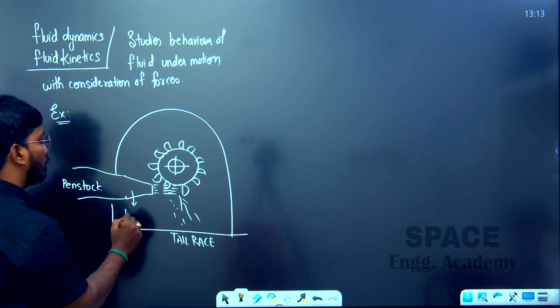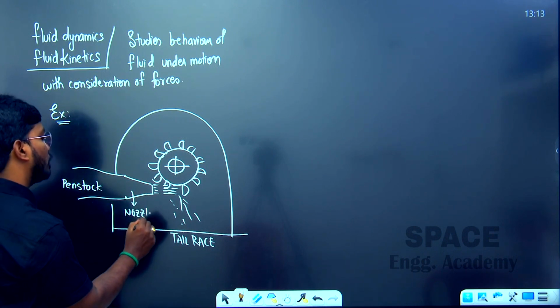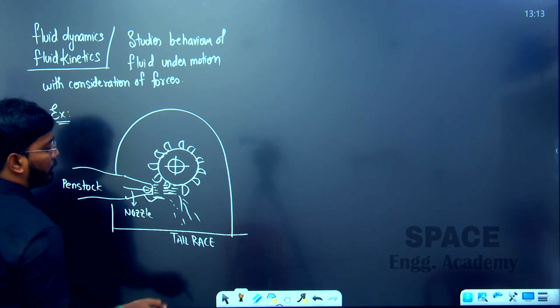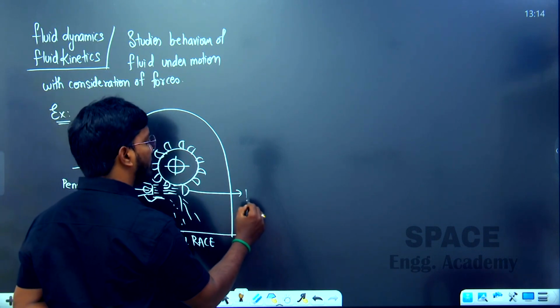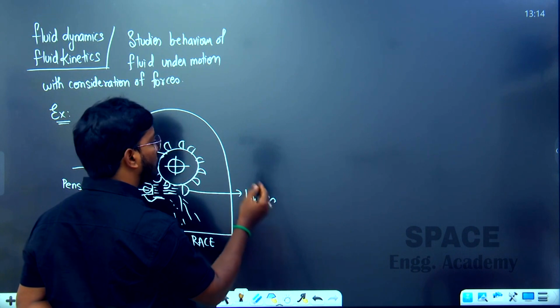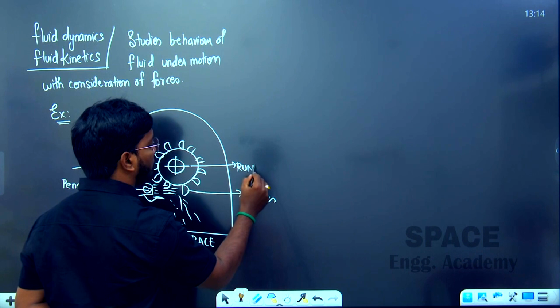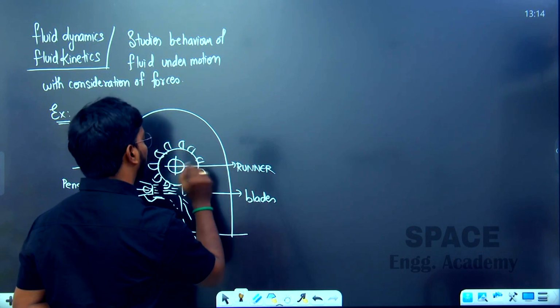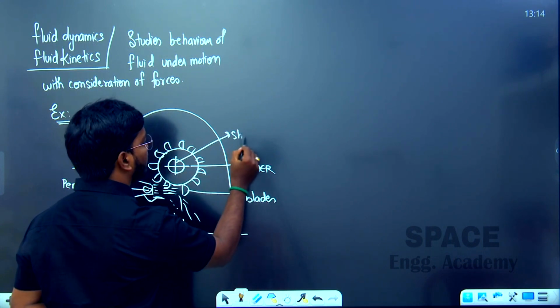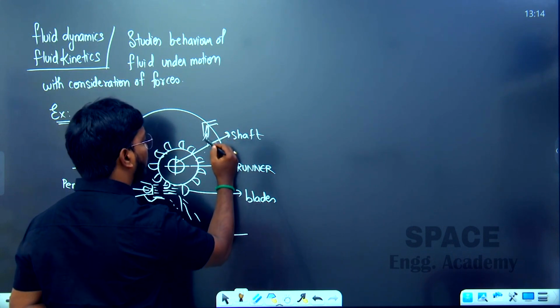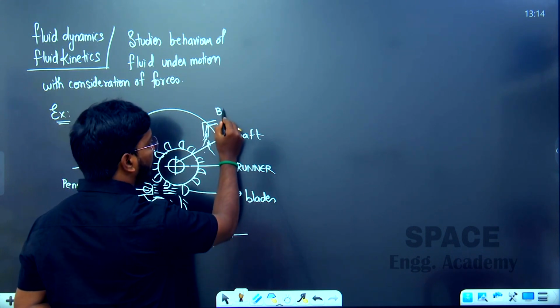Here we have the nozzle. Inside, the nozzle will again have a spear rod. Here we will have a deflector plate. These are blades, double hemispherical ellipsoidal blades. Then it is called a runner. Then at last we have the shaft. Here we will have a jet transferring water from the reverse direction, that is the braking jet.